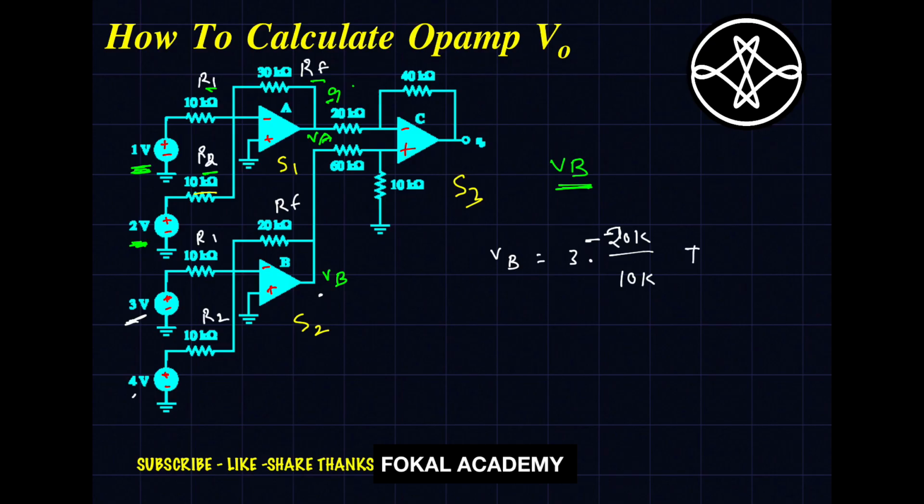plus next 4 volts. The output voltage due to 4 volts is 4 into minus RF by input resistance, that is 10 kilo ohms for 4 volts. That is, R2 is 10k here due to 4 volts.